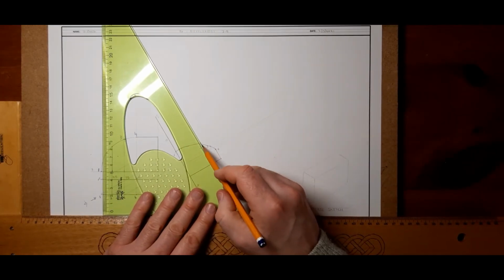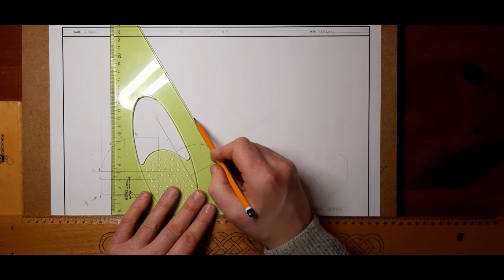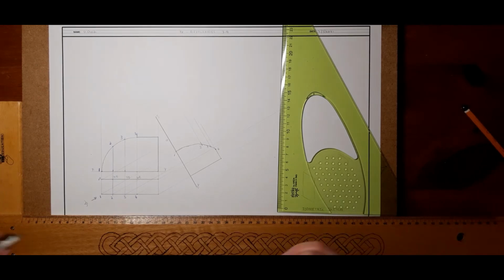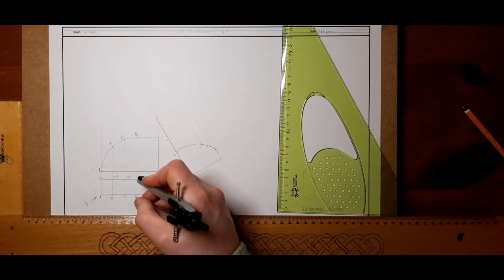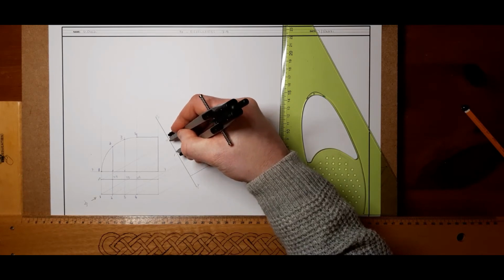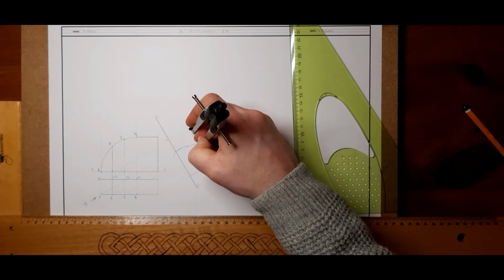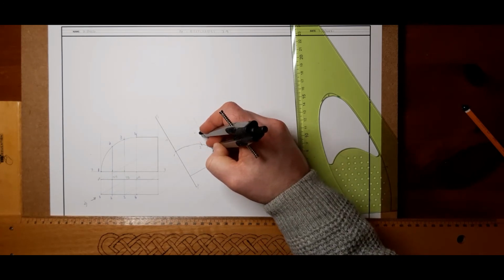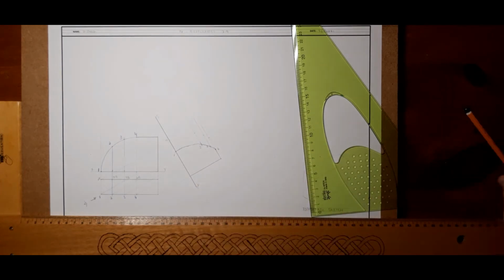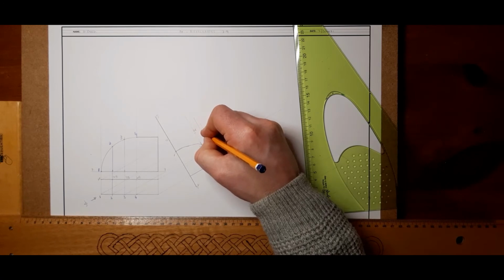And I'm just going to do a couple of light parallel lines for a moment. And the distance between these now will not change. So if I mark off the distance between 1 to B there, it's slightly foreshortened in this view, this auxiliary view. It'll be the same. That'll get me 2B. That'll get me 3B. And that'll get me 4B there. So I can mark them in now. And please label your drawings.